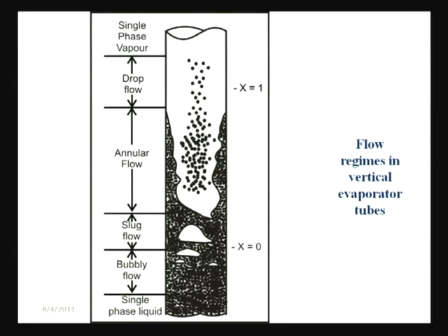The other thing is the presence of some droplet flow, which was not there in that particular case. As I had already told you, there is an inherent tendency of liquid to wet the pipe wall. So, therefore, this droplet flow pattern does not occur under normal circumstances in unheated tubes. So, these are the two basic differences between flow patterns in heated as well as unheated tubes.